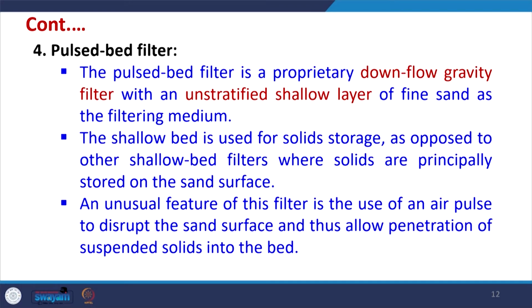Then we have a pulse bed filter also. It is a proprietary type of filter, and it has an unstratified shallow layer of fine sand as the filter medium. The shallow bed is used for solid storage, as opposed to other shallow bed filters where solids are principally stored on the sand surface.